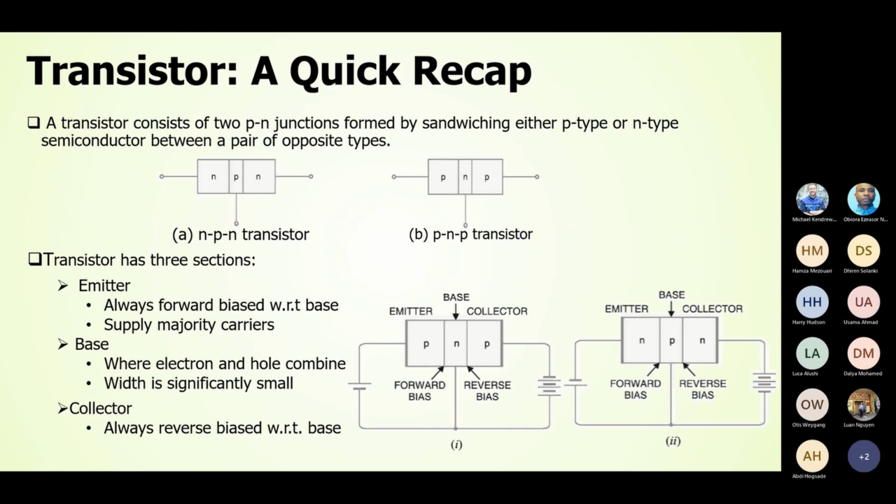Now, the Zener diode voltage regulator is simple, but it does not have a feedback mechanism integrated into it. So we can use a transistor to integrate a feedback mechanism. So what is a feedback mechanism? It's like a control. So you compare something with a reference and you calculate the actual value. From that you get the error, and that error you pass through a controller to get your desired output. In your coursework, you have to implement a feedback controller for a buck boost converter, isn't it? So a transistor can be used as an indirect or direct controller as well.